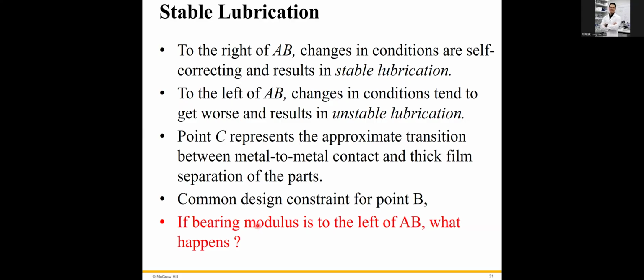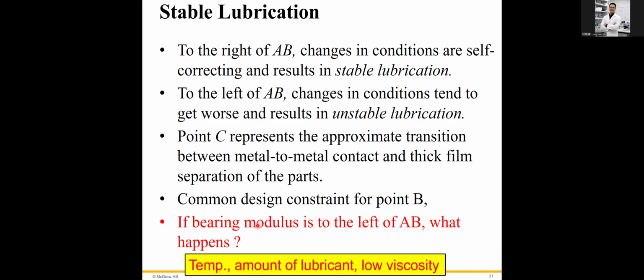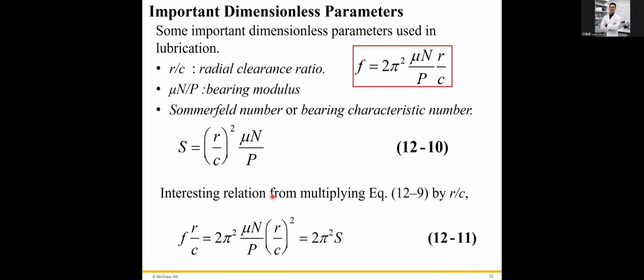So the thinner the contact, the metal to metal contact, that means the higher friction energy created. That means the higher heat created. And higher heat created means higher temperature, which causes low viscosity of the lubricant. So this is what I mentioned previously. Okay, so let's go back to Petroff's equation, right?